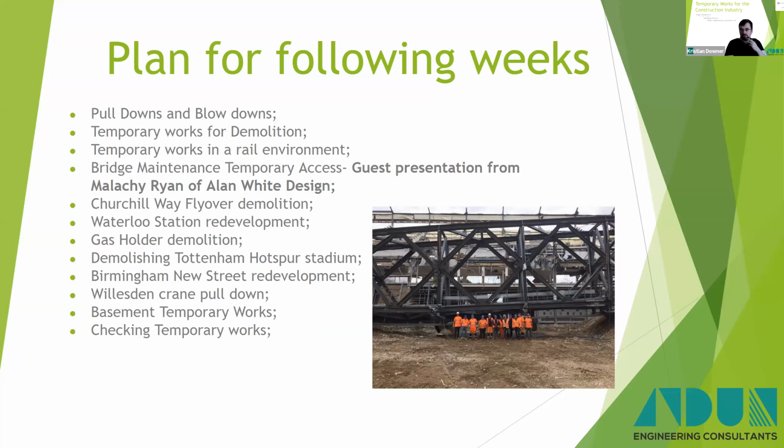Hi, Martina. Hi. Thank you very much. I'm getting involved in many smaller scale projects where very often I'm a principal designer. Very often we have some scaffoldings or crane lifts, bespoke or TG 2013 compliant. Would you say that temporary works coordinators and temporary works supervisors are required? What is your advice on that?